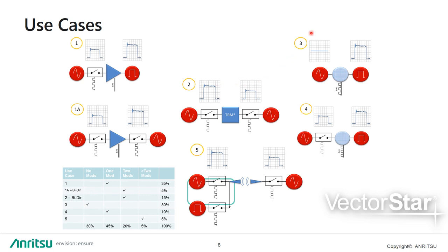Use case 3. On-wafer power amplifier device test with a CW RF and a pulsed bias. The user will utilise internal pulse generators to control the bias to the on-wafer device to compensate for the lack of availability of a heatsink and to minimise thermal effects.